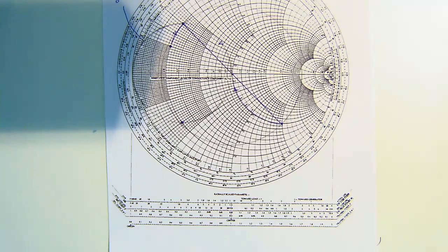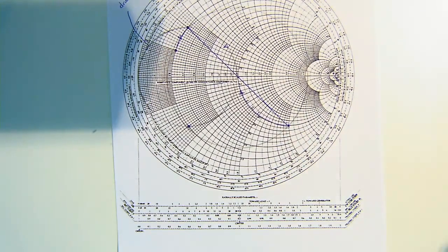What don't you understand? Perfect. So you don't understand how to draw that? You don't understand how to draw it or why to draw it? Why we're drawing it. Okay. What we want is to get to a line in susceptance, essentially we want the impedance to be Z equals 1, right? We want to end up at Z equals 1 in order to do the impedance match.